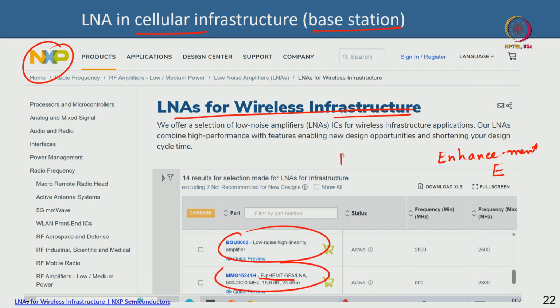So, all compound semiconductor devices, III-V such as gallium arsenide MESFET, HEMT, and gallium nitride, are inherently D mode. Their threshold voltage is negative. Silicon MOSFET is enhancement mode because the threshold voltage is positive. So E mode gallium arsenide, an E mode HEMT, a gallium arsenide HEMT by the way, is a very interesting concept because you are making a compound semiconductor device E mode.